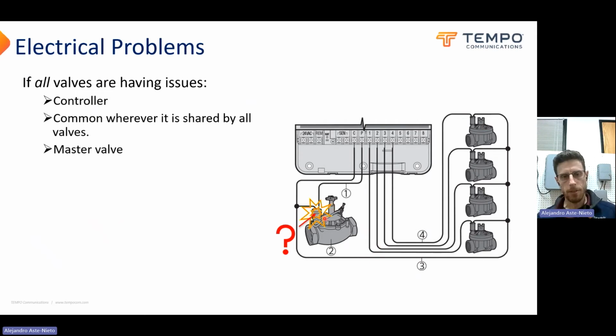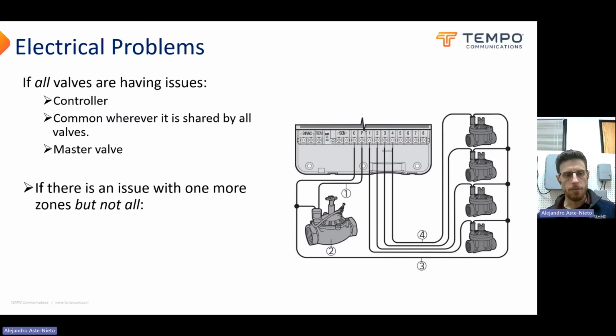And it could be the master valve. If the master valve is not opening, these are not getting pressure. The solenoids could be working properly, but there's no water pushing to allow through the valve. And there has to be water pressure to even engage the mechanical diaphragm in the valve out of the way of flow. So it could be any of these things. If nothing on your system's working, those are the places to look. We'll treat them accordingly.